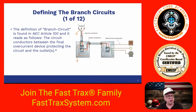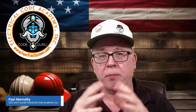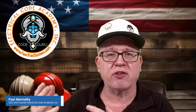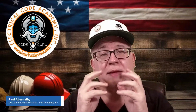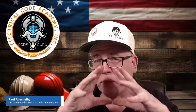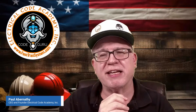Okay? Now, it is also extremely important for all of us to know that when we say outlet, we're not talking about the receptacle itself. We're talking about the point in the system where we take power from the system to supply utilization equipment. Now, it could be that the power from the building, the branch circuit, goes into a junction box, and then from that junction box, it supplies power to utilization equipment. Well, the outlet is the point where that power is taken from the building system to that utilization equipment. All of this is defined in Article 100 of the National Electrical Code.